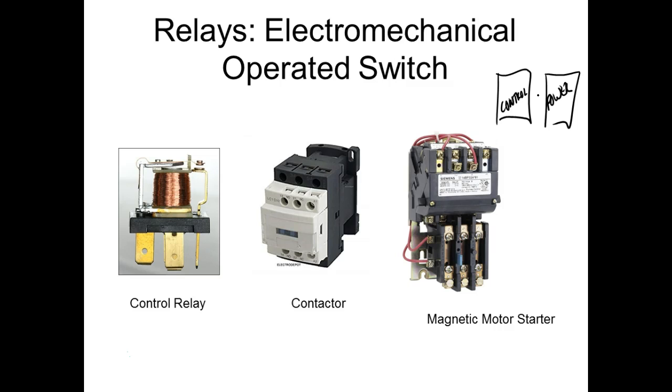But then we get out to the power section. The power section is where you're going to have high voltage, and we're going to put this in a cabinet over here by itself. So you can work inside the control cabinet with standard PPE. You know what PPE is, right? Yeah, personal protective equipment. Over here, working on the controls for your PLCs and everything, this will be low voltage, so you can work in there without putting on your glasses.